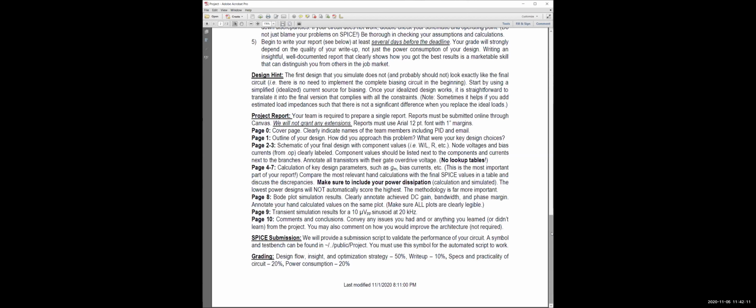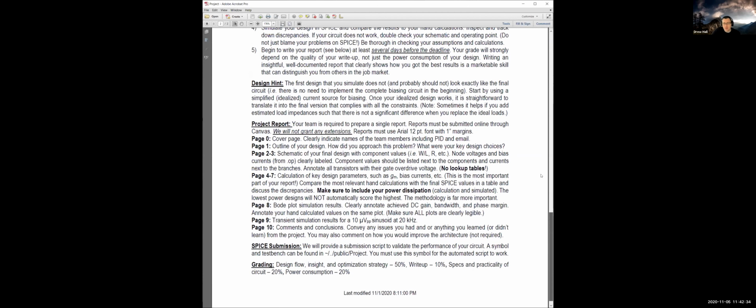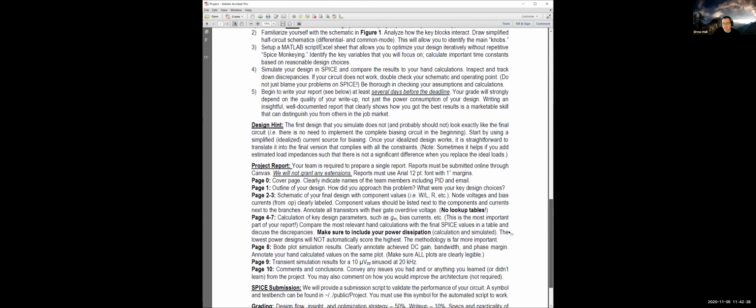So when you mentioned the design flow, you said start off with the amplifier design, then the second stage of the amplifier, then maybe the bias, and finally the frequency response. So how do you start off with the design of the amplifier when you're not much concerned about the frequency? Yeah, you're absolutely going to be concerned with the frequency. The frequency planning is probably one of the very first things that you have to do in this type of project.